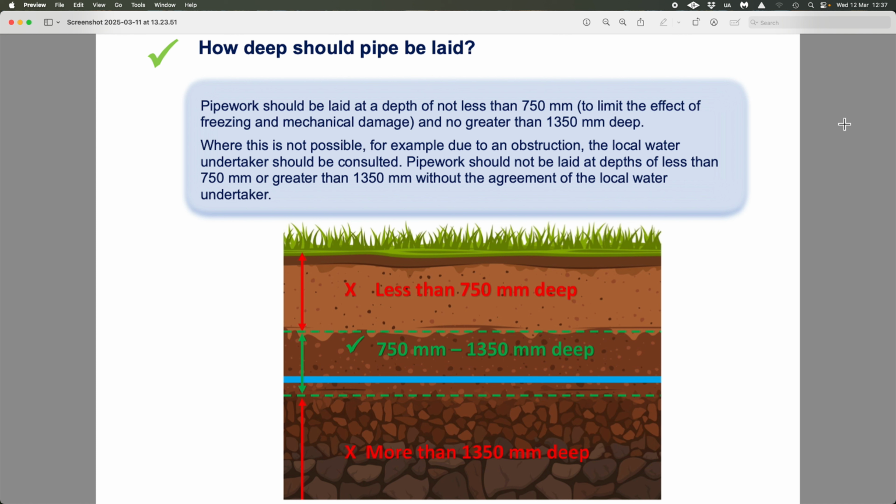So that's one point. So when we do the calculations on this, and we're doing temperature rises, we know that we've got a temperature rise within hot water, a combination boiler, of a DT of 35. That is our general rise of temperature to get it to our hot water coming out of our tap.